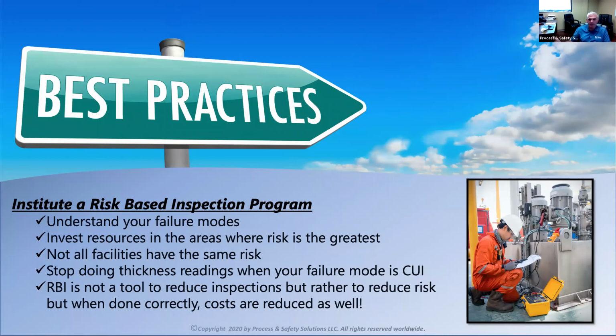There's usually a specific temperature range where you're going to see a lot of corrosion under insulation. Also, typically on systems that go through hot and cold, or where insulation gets wet and dry and wet and dry because of those temperature swings.